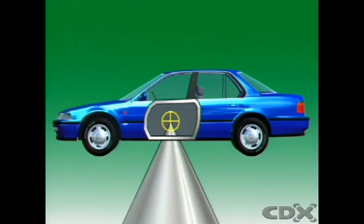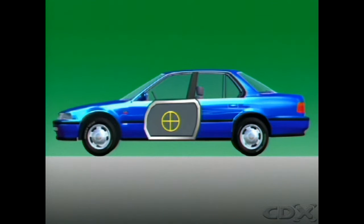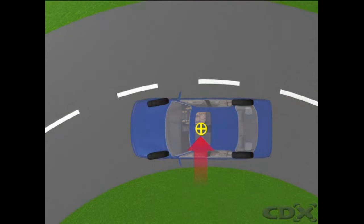The center of gravity is the balance point of the entire vehicle. Its actual position depends on location of the major components. It is always located above the road surface and between the tires. When a vehicle is cornering, this is the point through which all centrifugal force is assumed to act.